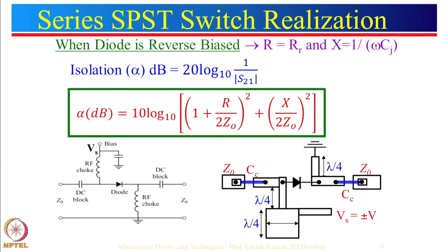In fact, many a time we put multiple capacitors instead of a single capacitance over here. These multiple capacitances can be of the order of, let's say, 1 microfarad, which is for smoothing out the ripple, and we may also put 10 nanofarad and even 100 picofarad. These are basically to take care of the transients, because remember it is a switch. The switch will be going from on to off or off to on, so a lot of transients will come into the picture, and these transients are at very high frequency. So you need small values of capacitances to take care of these transients.